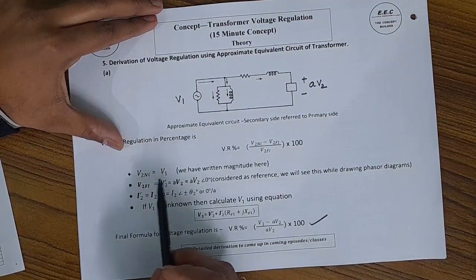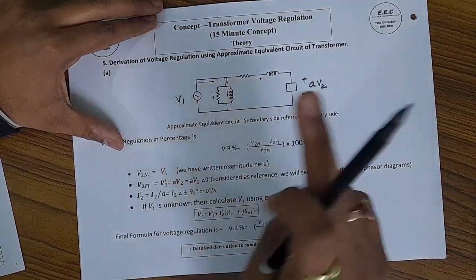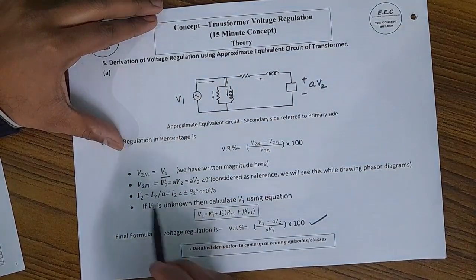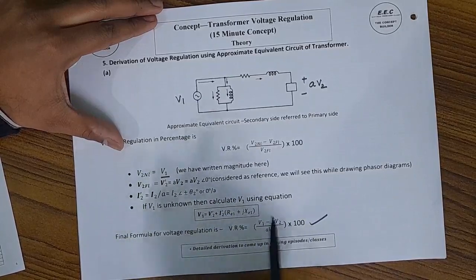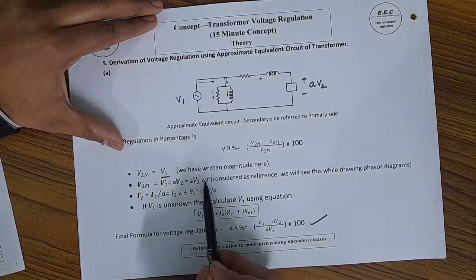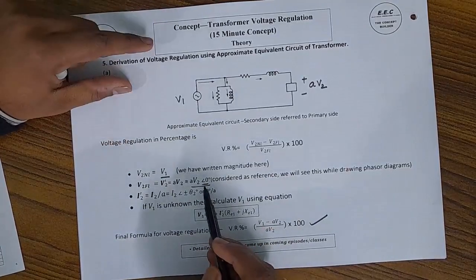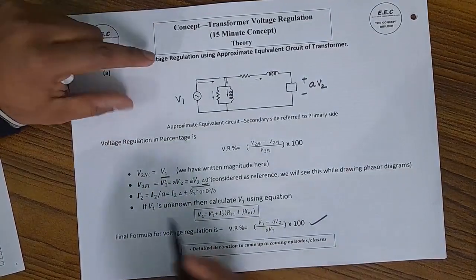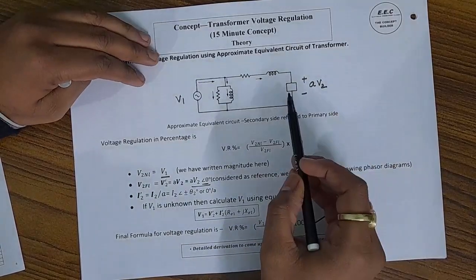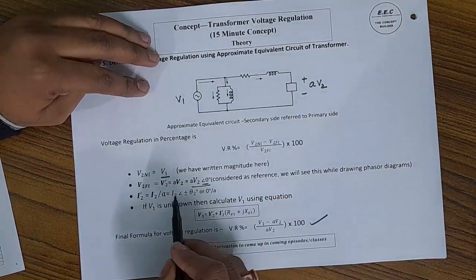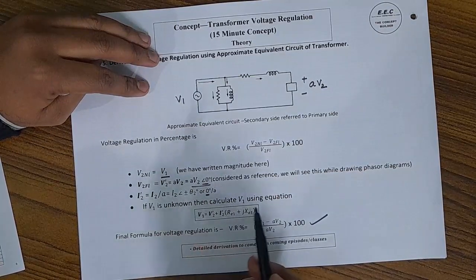Now what is V1 here? V1 is going to be the voltage at no load. When we remove this, we are going to get V1 as the voltage at no load. I have written the magnitude only. And V2 is the full load voltage, which is written as AV2 angle 0 degree. Why are we writing it as angle 0 degree? Because while drawing the phasor diagram, we are going to consider V2 as the reference phasor, and I2 can be this. We are not aware of the load, what kind of load we have applied here. So I have written it as I2 angle plus or minus theta 2, or 0 for unity power factor load.